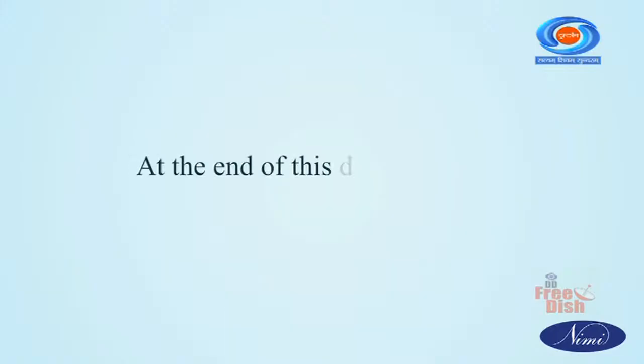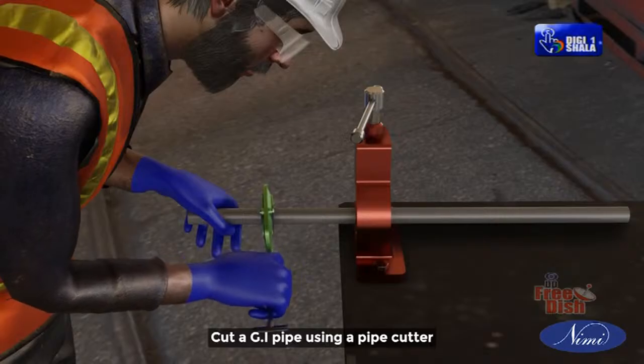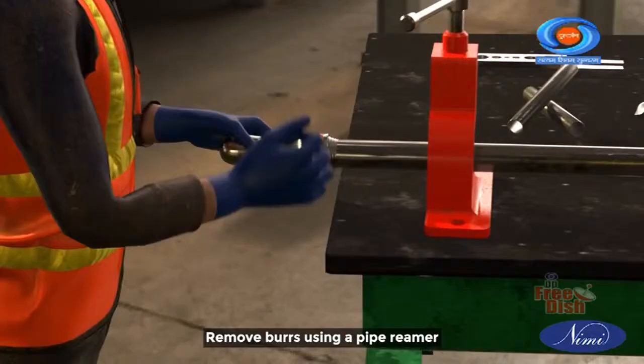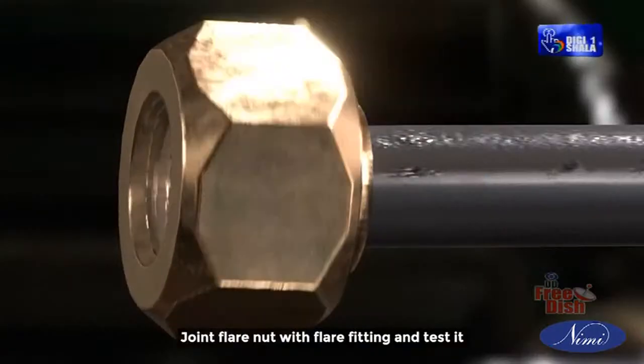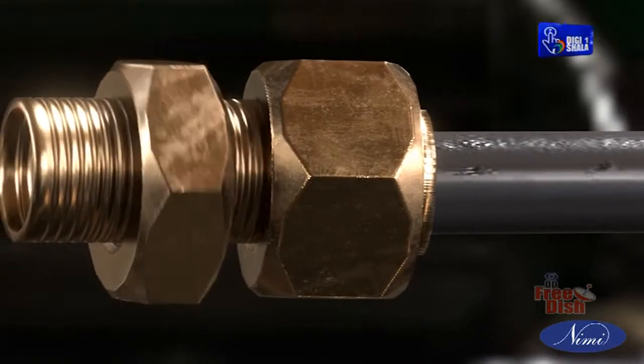At the end of this demonstration, you will be able to cut a GI pipe using a pipe cutter, remove burrs using a pipe reamer, flare the end of the pipe, join the flare nut with the flare fitting and test it.